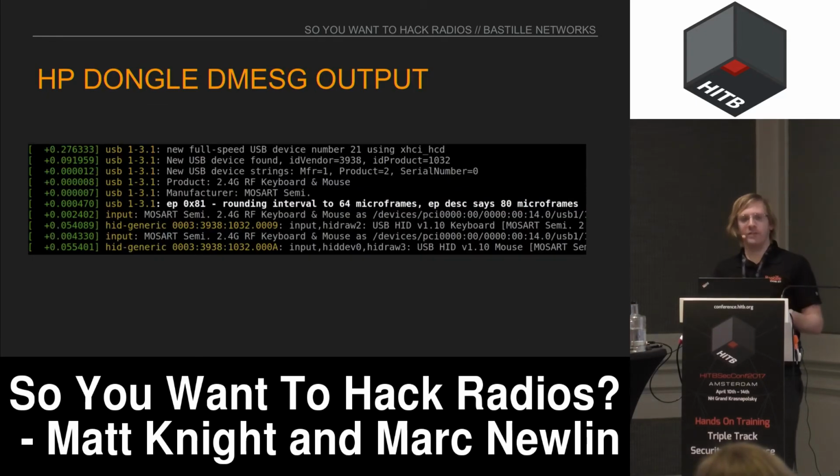And because this is a device that can talk to a computer, we can plug the dongle into a computer to look at the dmesg output. In this case, it identifies itself as a Mosart Semiconductor device, and it turns out that's just the vendor which makes the transceivers in this set.